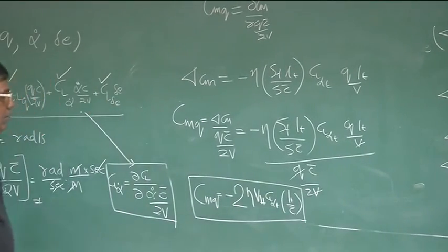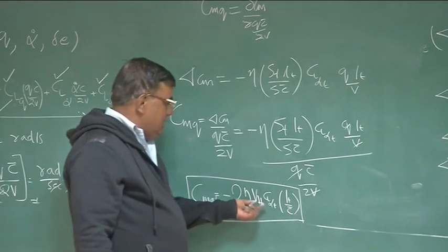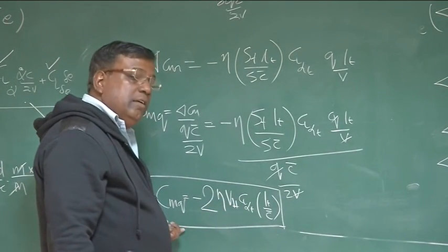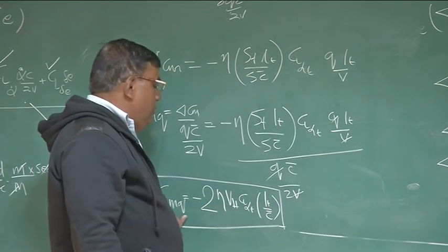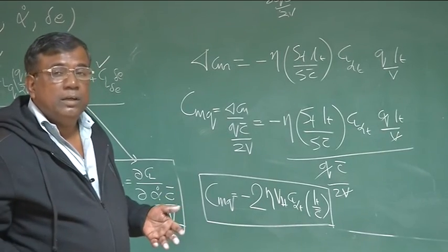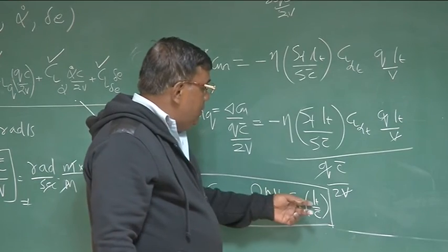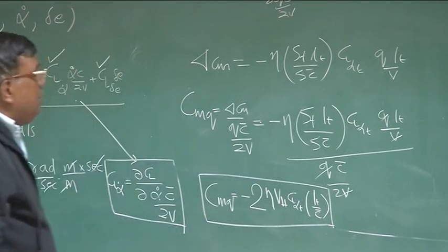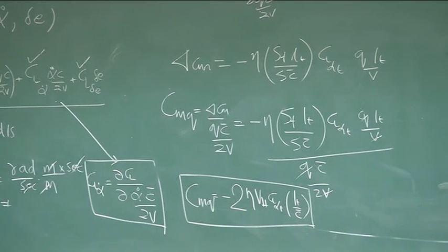You could see one thing very interestingly, that if we change L_T, if we change V_H, that means if you are changing V_H, CMQ is largely affected. And also if you change L_T, this also will change CMQ. Suppose you want to increase CMQ. CMQ means what? Damping. No? So this will tell you that if I want to increase damping, increase L_T or increase V_H or both. Okay? This is extremely important, what you call the derivative. I am now focusing only on the derivative.